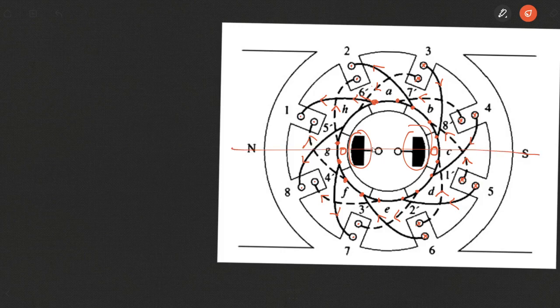Fine. So we place the brushes at these two locations so that from one brush the current is moving in, and from another brush the current is moving out. So the current, and accordingly the voltage that will be available here, will have the polarity plus and minus. Current is actually moving out of the plus and getting into the negative segment.